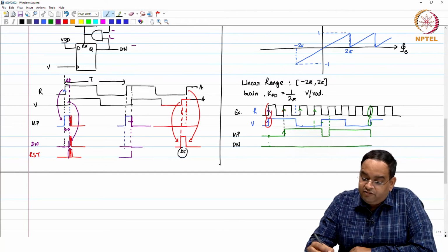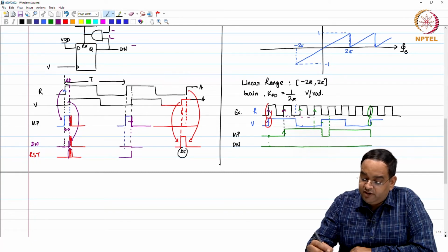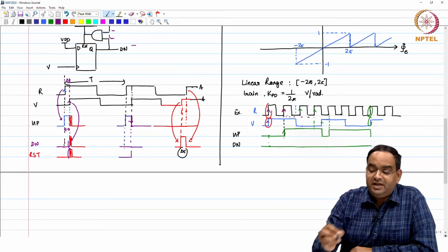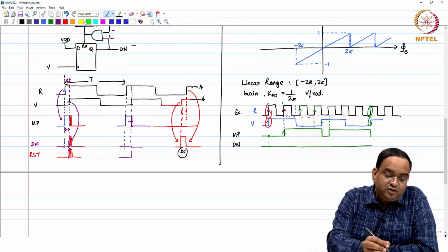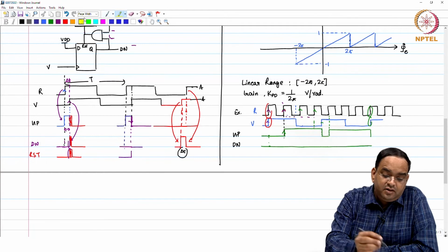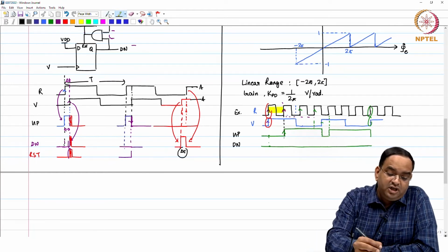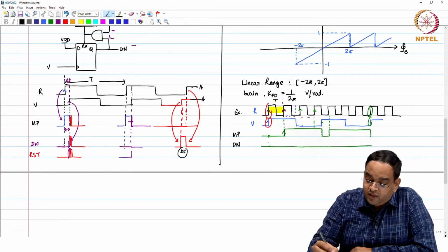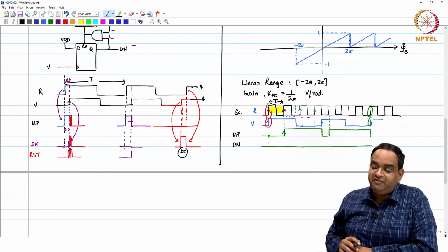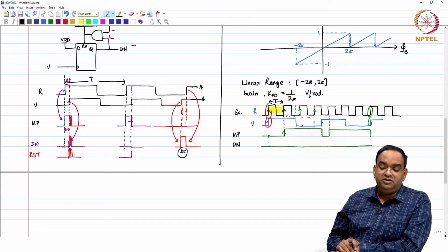the phase error which you are measuring at any given instant of time, one thing is we are measuring the phase error with respect to the reference clock period. As I told you, you are always measuring the phase error with respect to the reference clock period. Okay. So, in the first reference clock period, you see that the error is 0, right, because they both are aligned.